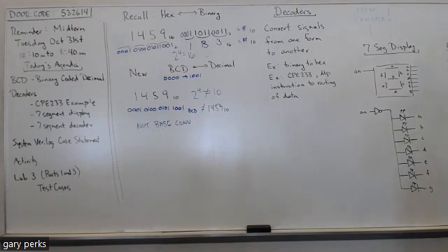And what does the select input of a mux determine? What the output's going to be, right? It's going to choose which of the multiple inputs the output is going to be equal to. So you see, the reason why this is called a decoder is because this decoder is taking bits of an instruction, and then by controlling the muxes through the select inputs, it's determining how the data flows through the circuitry so that the instruction actually occurs.